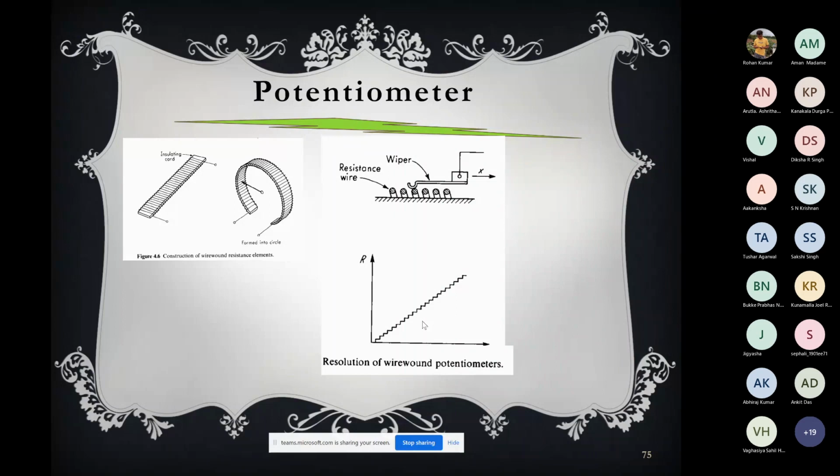That is also one constraint. So the key takeaway is, when you are going to maximize something, you may realize that it is also limiting some other thing. So you need to have a trade-off. For example, if you are trying to increase the sensitivity, you increase the input voltage, but that is going to limit the maximum power dissipation. Okay, and for that you have to limit the input voltage.